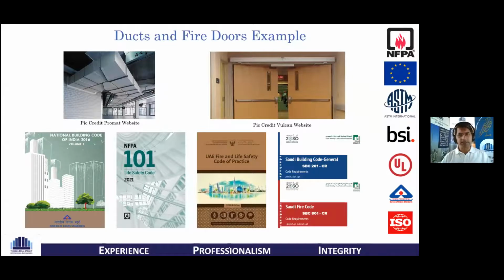I mean, I found an ASTM standard or maybe one or two others, but when I scanned the Saudi building code and even the American IBC codes, I realized that the approach to validate and ensure that the fire does not spread through the duct is different in the American code.